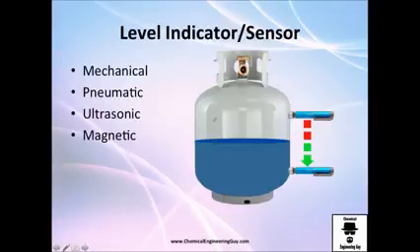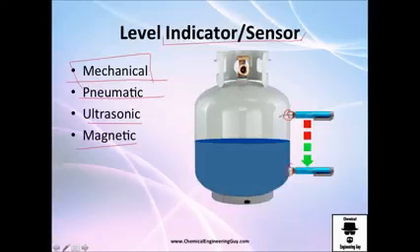You also need a level indicator or sensor, for example these and these. There are plenty of sensors. I'm not going to talk about that because that is more into instrumentation and control of processes, but you have pneumatic, ultrasonic, magnetic, and of course mechanical. So this might be, you don't feel it, so it's not high, but this one you feel it, so it's not empty. It's between empty and full. Very fancy. But of course, if you add another one, you can tell it's either half, more than half, less than half, or empty.